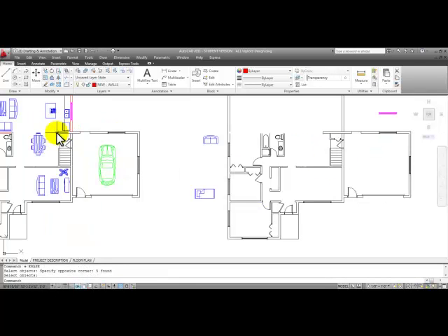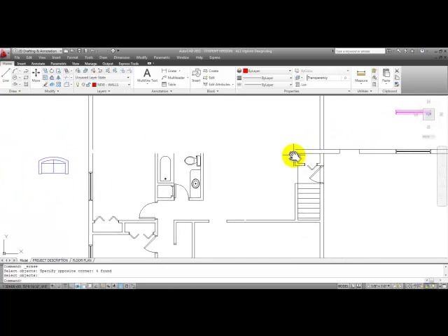To close this corner, we can erase these small lines that are an extension of this corner, and then we said that we could use the fillet command with a radius of 0 to clean up these corners as an option. You can start the fillet. Looking at your command line, the radius is 0. I can select this line and this line. And I believe this piece right here is just a small piece that you can erase.